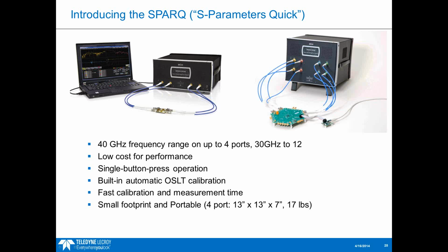So if you have a 5 gigabit per second USB 3 signal, Nyquist is 2.5 gigahertz. And there's a rule of thumb we use in the oscilloscope industry for making recommendations on how much bandwidth you need. Typically, you want to make sure you're capturing at least the fifth harmonic, and you can use that same rule of thumb when you're looking at S parameters and figuring out how much bandwidth you need in the channel.